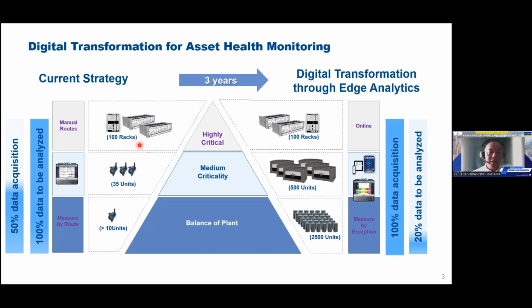So over here you can see traditionally or currently, or maybe something that is in the past for some people, a lot of the machines are monitored. Maintenance of their machines is done this way. Typically, the most critical assets for your power plants, of course, your turbine, for chemical and petrochemical plants, your compressors, for mining, your SAG and ball mills. Definitely, there's going to be some kind of online monitoring there. So the most critical machines have online monitoring that is taking data 24/7, protecting the machine, and sometimes there is also a bit of diagnostics.